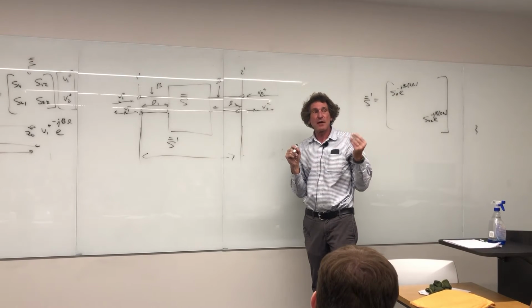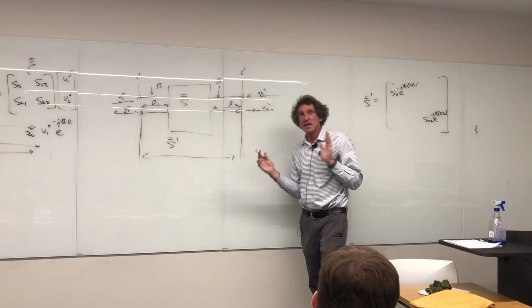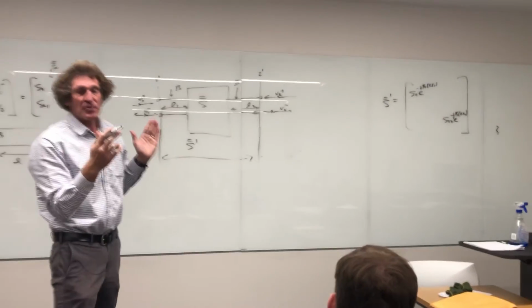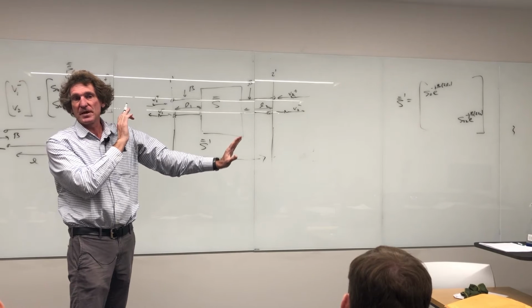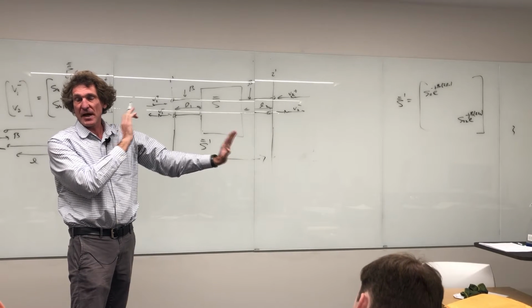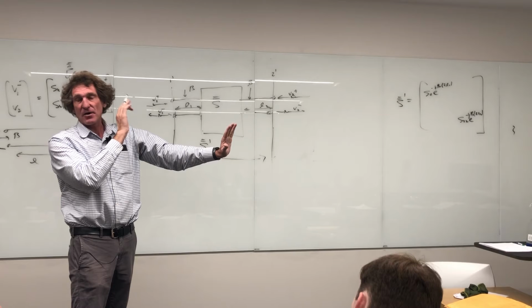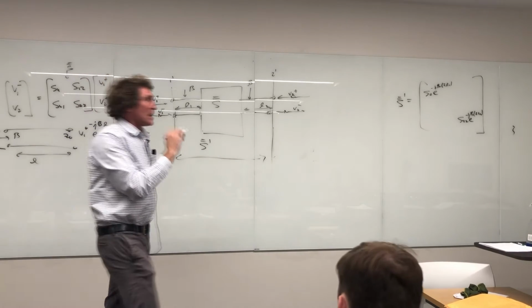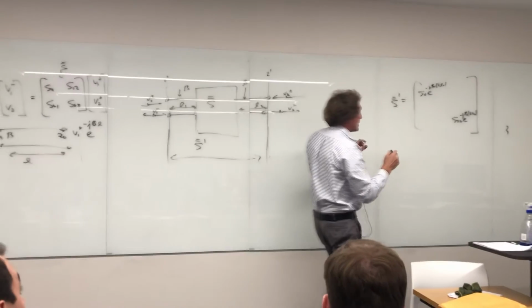This really just accounts for the phase delay when you move the ports. And it's almost invariable. It's something you're going to have to deal with when you're doing engineering work. You can't always get things exactly where you want them, so you have to have lines that I call delay lines, but they affect phase only. Got me on this?